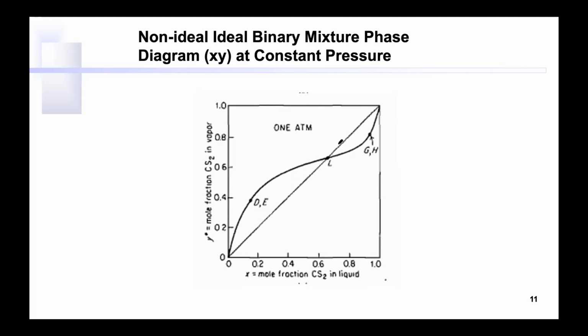So for example, if you're in the lab, you will find a lot of ethanol, 95%. We call it ethanol technical grade, because ethanol and water have an azeotrope at 95. Ethanol technical grade is cheap because it only needs one stage of distillation.